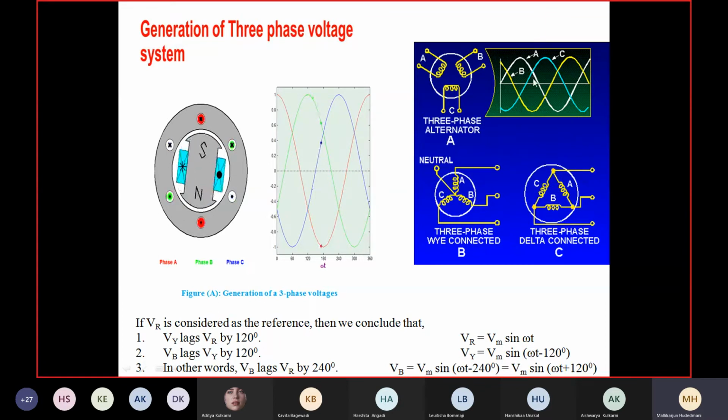Why trace it this way? The white one is one cycle, 0 to 180, and the first mark is 60, 120. So late by 120 degrees, you start the second wave like this. You complete this, and late by 240 degrees, you can see the last one, yellow, beginning here. This is how it is drawn. You can see these markers running on this: red, green and blue. They are internationally recognized as RYB in the Asian continent and UVW or RST in the European continent.